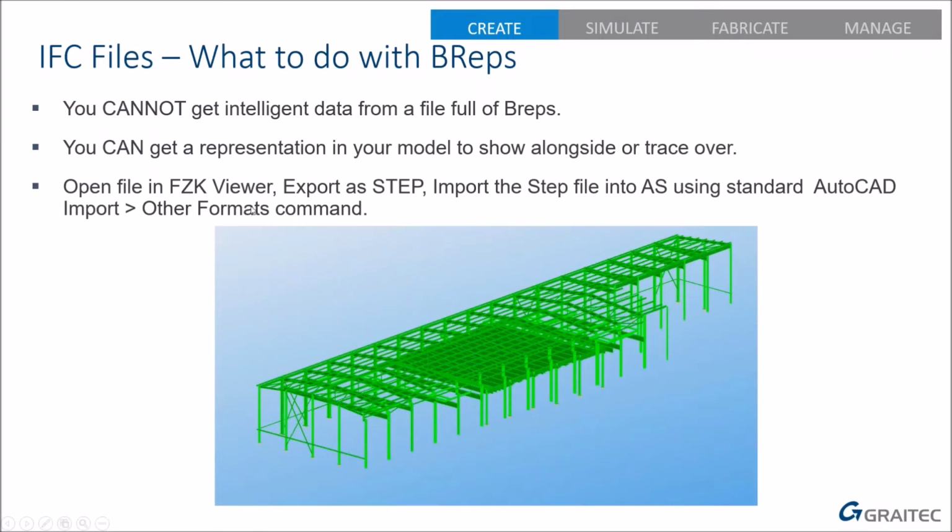command. That will import it into a blank file, or into whatever file you got open. Again, I recommend you import it into a blank file, which you then insert as a block into your current model. And there it is. The downside is that's all one color, all on one layer, whereas the other one had it look a bit more pleasing cosmetically.